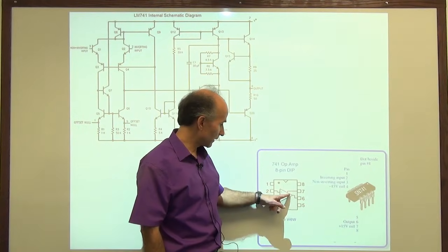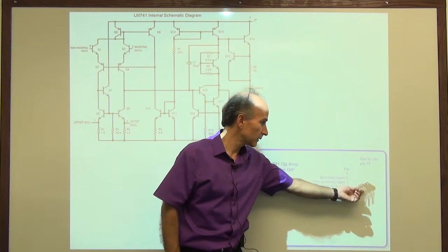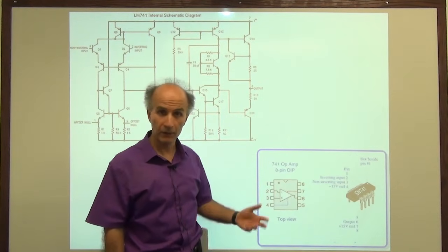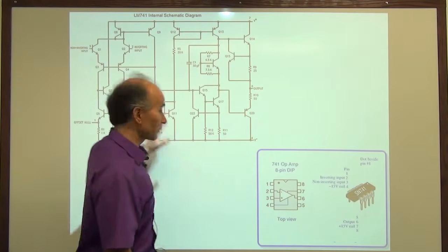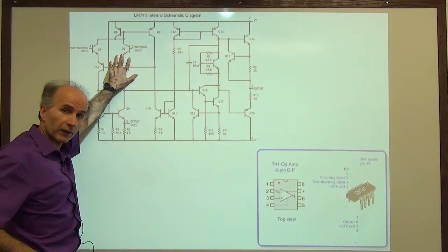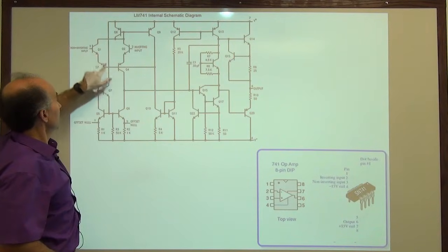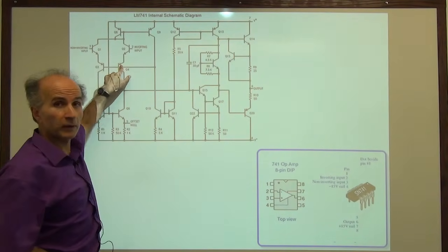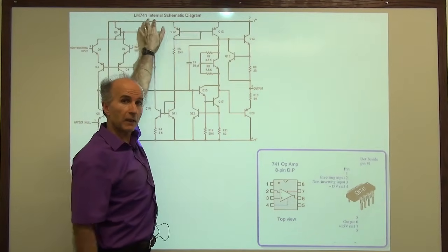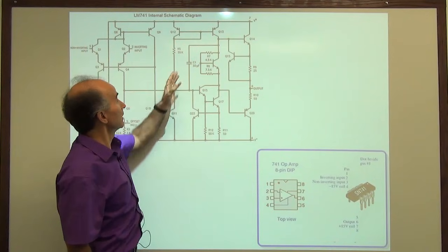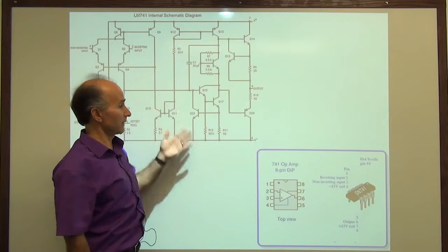Now, if we go and dig inside this amplifier, there's a little chip inside. The chip is very small, maybe 1 millimeter by 1 millimeter. If we go and look at that chip, we see something interesting. Here's the circuitry that we see inside that amplifier. So you see lots of bipolar transistors. We have NPN, we have PNP. As I said before, typically the PNPs are upside down because we assume this is the positive rail. This is the negative rail, meaning positive supply, negative supply, or just that this is more positive than this.